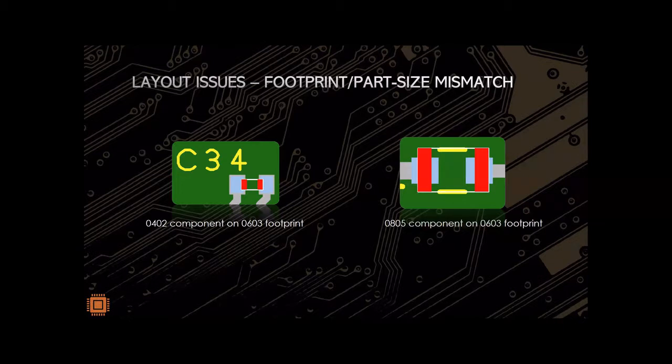And then looking at the example on the right there, you have an 0805 component on a 0603 footprint. Although that part is placeable, it's not ideal if you're planning on going into production runs, because we're trying to give you optimal resolutions for your footprint on the board. So that's the type of recommendation, even though it's not a hold, that we give you the option of, you know, go ahead and place it or go ahead and change it to an 0603 part.